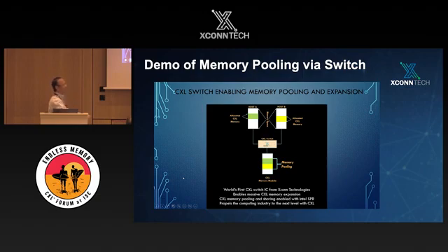We just use one memory device to show that, through the switch, they can share it. But of course, for memory pooling, we are going to put multiple CXL memory devices into this pool. For this demo purpose, we just use one single device. And these two segments from host A and host B map to different locations in this CXL memory module, all right?